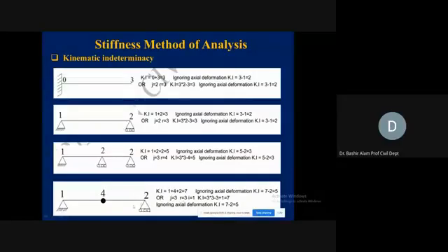Again, at the roller, if we take axial effects into consideration, it is 2 degrees. So 1 plus 4 plus 2, it is becoming 7 degrees, which is written here. If we ignore the axial effects, it means 7 minus 2, it is 5 degrees now. So 5 degrees now, ignoring axial effects; with the help of the equation, you can find out, and we are getting the same result, 7 and 5.